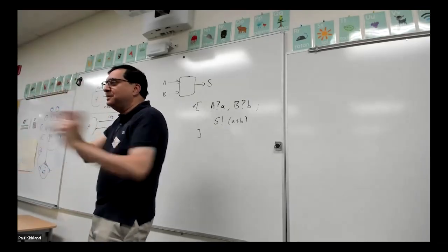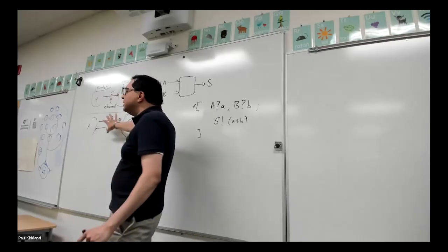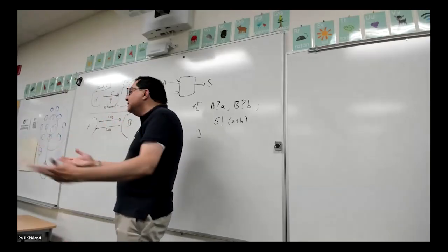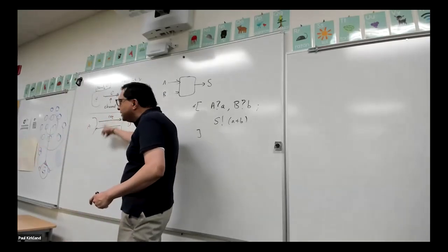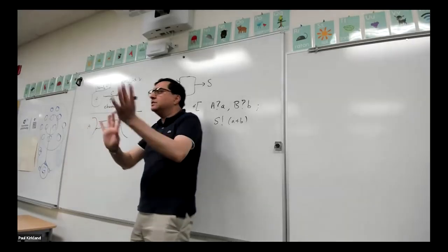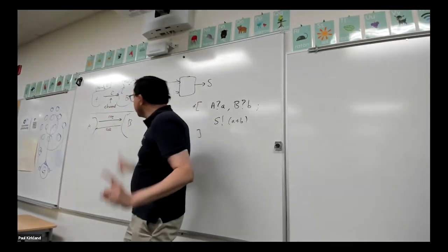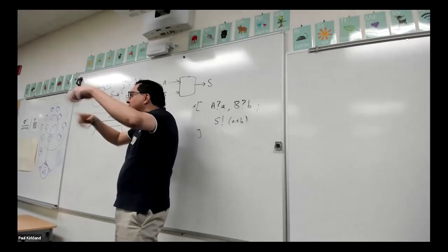So let's add data. You can do this as 4-phase or 2-phase. 2-phase means when there's a transition here, there's a transition here, and I'm done. That's the 2-phase. You can also use one wire, but then you have to drive it from both ends.